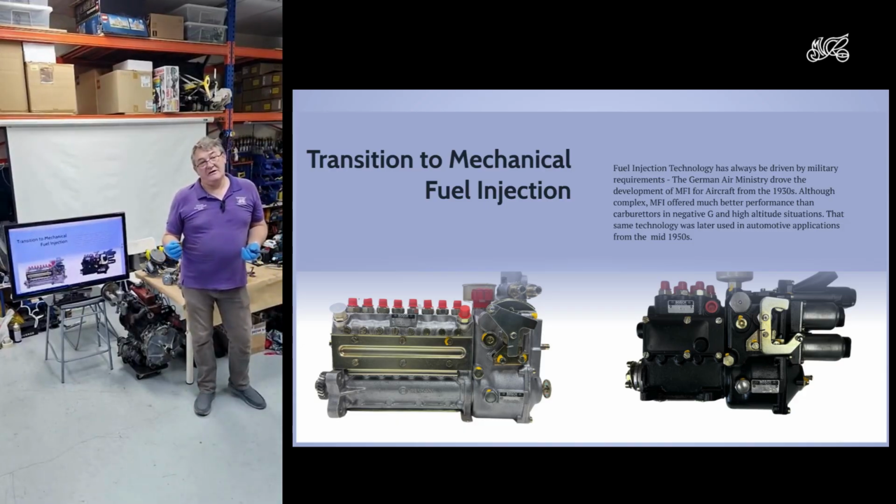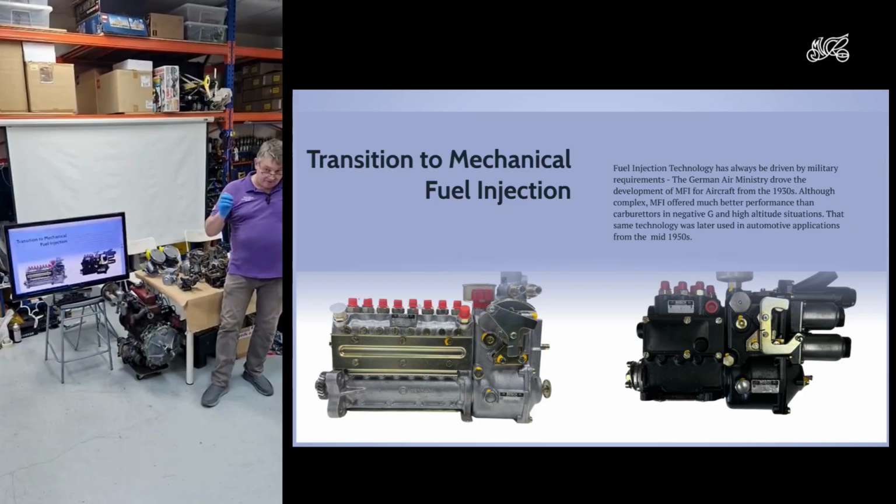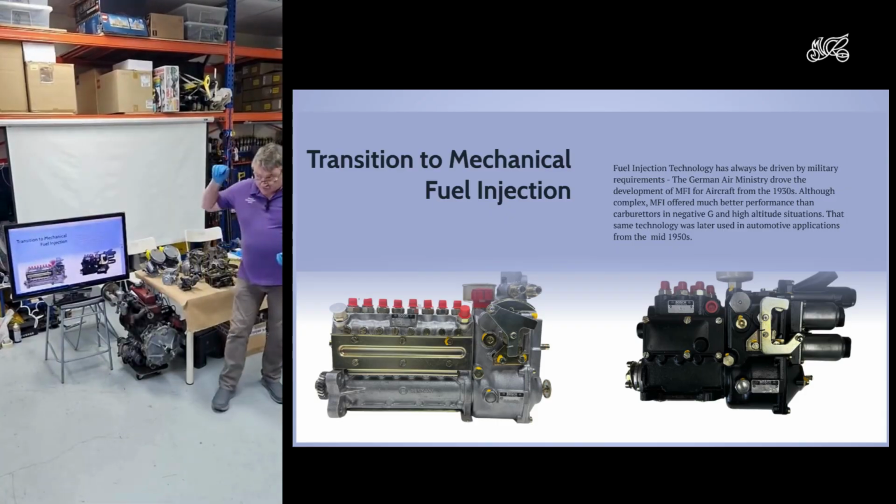Yeah, so these are important factors in designing an engine, and the British felt that the charge cooling of a carburetor was more valuable than injection, because you don't get any charge cooling with injection, because you're injecting straight into the cylinder in this case.